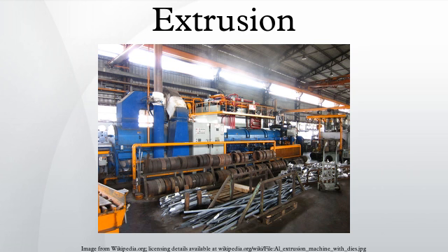Often more than 100 size required to extrude copper. Lead and tin: pipes, wire, tubes, and cable sheathing. Molten lead may also be used in place of billets on vertical extrusion presses. Magnesium: aircraft parts and nuclear industry parts. Magnesium is about as extrudable as aluminum.